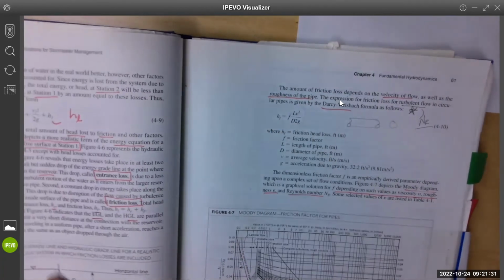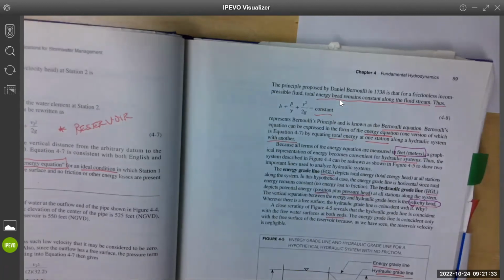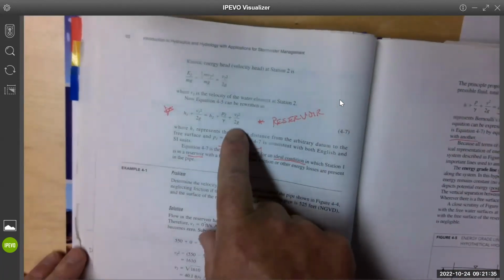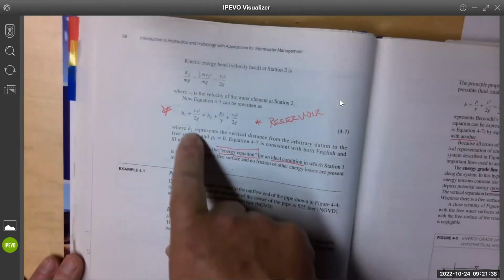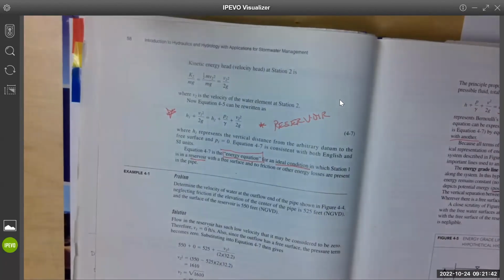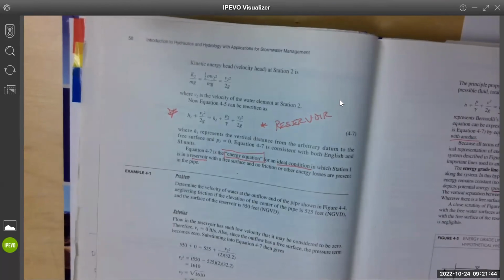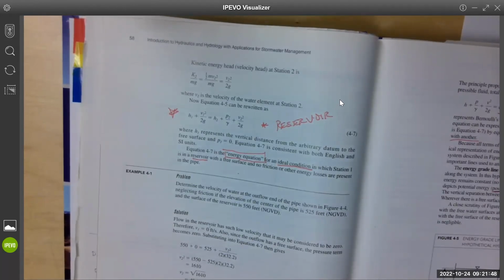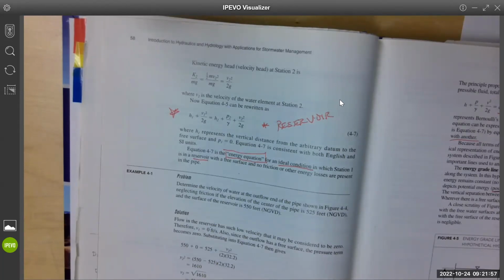Yeah. So here's the thing that's interesting, there's gauges that measure these kinds of head losses or heads. So in a system, you can go, okay, we have a potential energy here, a potential energy here and a kinetic energy here, and we have certain things going on here. We work that equation that says one side equals the other. And if we calculate that through and it doesn't equal the other, then we have losses.